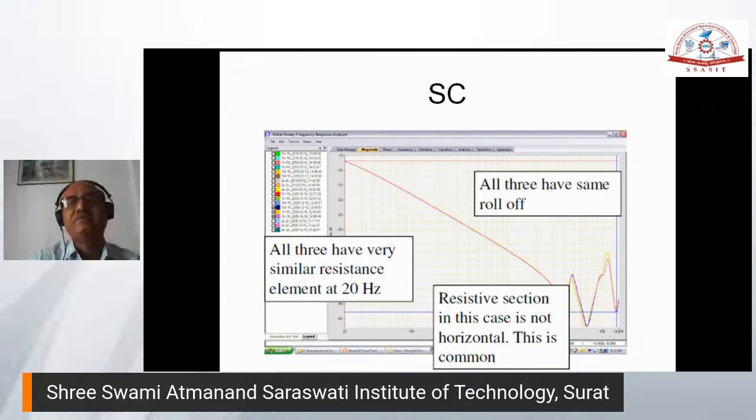Now in one frequency you cannot check it, because the fault nature will be different, and different zones will create different frequencies. So this is basically for winding deformation, winding-to-ground deformations, and turn-to-turn deformation. Turn-to-turn fault is indicated, turn-to-ground fault is indicated. So these mechanical variations are detected by some electrical parameter measurement.